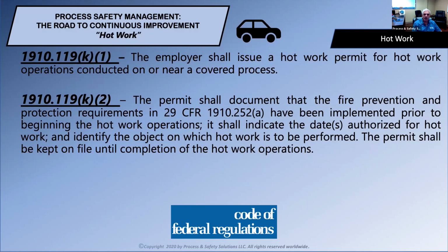It also indicates the date authorized for the hot work, identifies the object on which the hot work is being performed, and the permit shall be kept on file until completion of the hot work operations. This one's pretty important. A lot of facilities that I go into when we do compliance audits, I will ask for their previous hot work permits. Some of them will say, well, we only keep them up until the point where the hot work is completed, which according to the PSM standard would be perfectly fine. There's no requirement to keep it beyond the completion of the hot work operation itself.